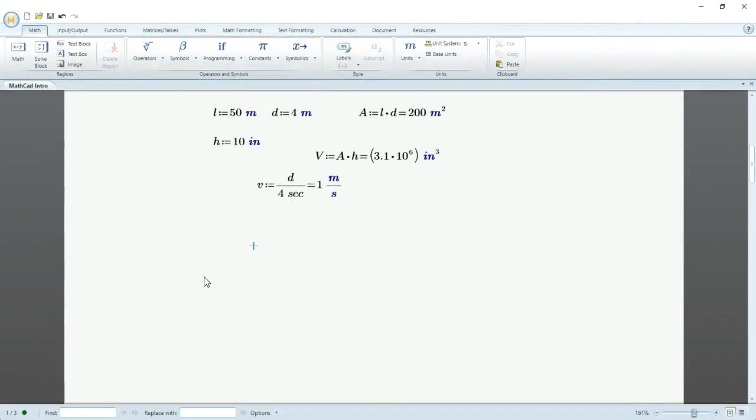Okay, I've cleared up our workspace, and we can now talk about units of force, stress, and pressure, and mass. So let's type force. Let's make that 10 kilonewtons. When I type force again is equal to something, we have newtons, but let's say we want this to be in pounds. So I'll type LB, and I get this weird thing that's happening, and what we see is that pound LB is actually a unit of mass, and then we have mass times our acceleration.